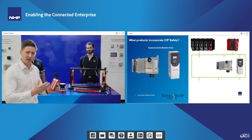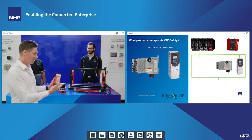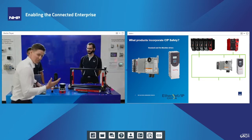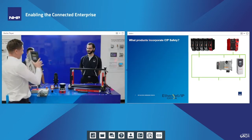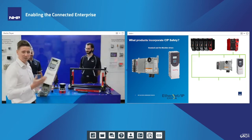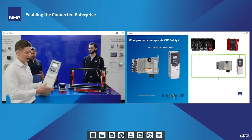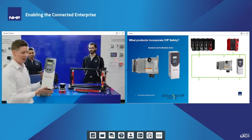On top of that, you can also have some safety I/O. This might be in cabinet, in field, but again, you can tell clearly from the red coloring that this is a safety rated I/O module. So when we talk about what products can we incorporate with this technology, I'm jumping ahead of myself there, Stefan. That's all right, Jack. So we've got here a PowerFlex 755 drive. We do have those in multiple sizes, but all our drives, our VSD drives, do incorporate that CIP Safety technology. And I guess the biggest feature which Dan mentioned is they can be daisy chained just with a single Ethernet cable coming in and out.